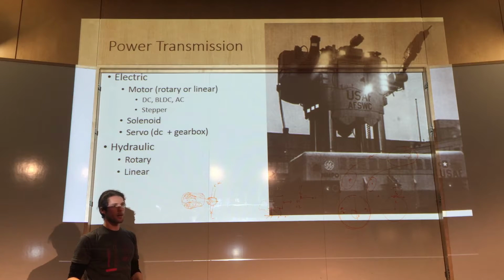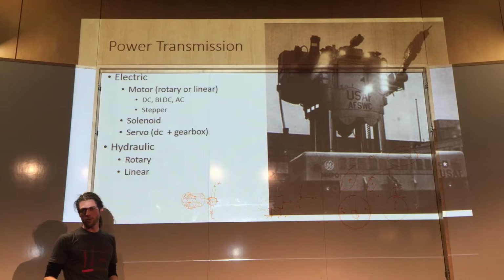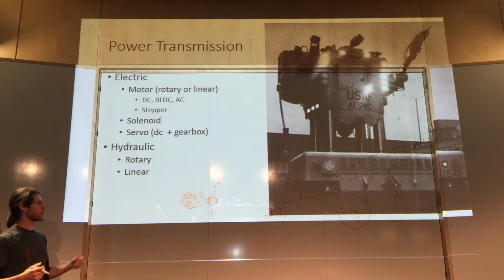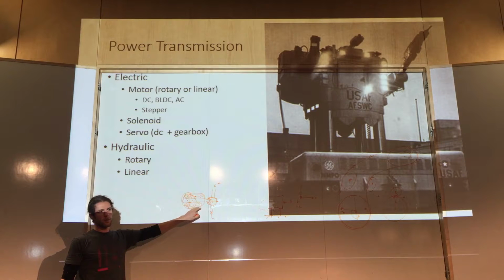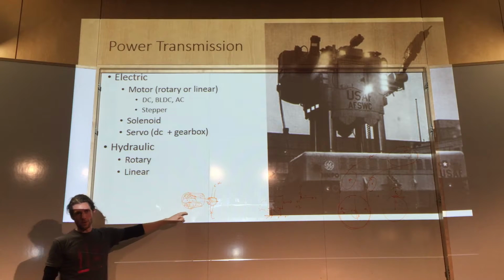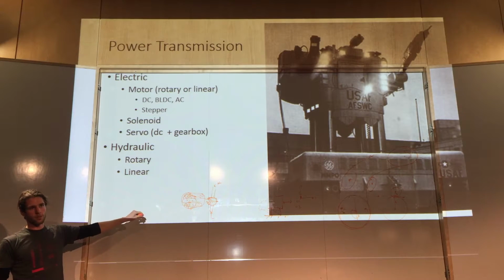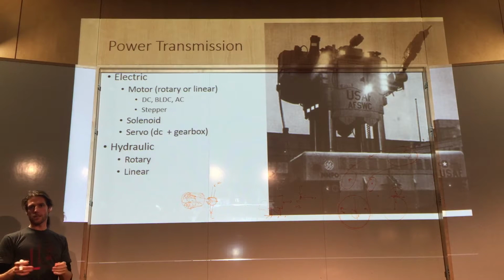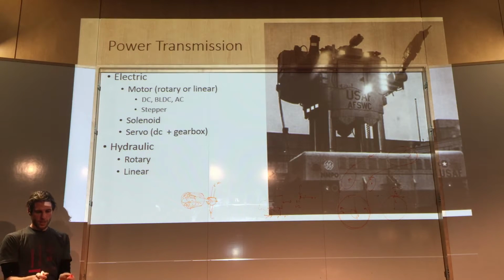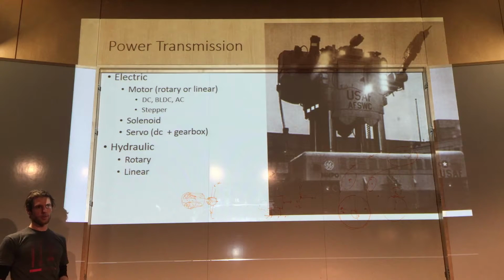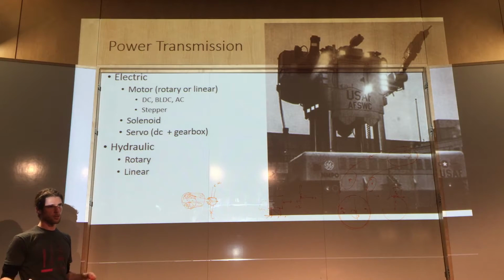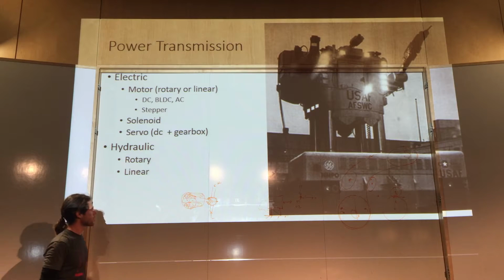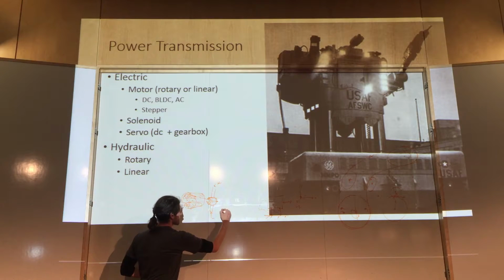And that gives high frequency noise, which ends up generating a whole bunch of noise in your system. So if you have a lot of digital electronics near your motor, you're probably going to end up getting a bunch of noise popping off from it. And right now, if any of you are building any systems with DC motors for your final projects, I highly recommend trying to get all the stuff that you're going to be using running. It doesn't have to be all finished and packaged, just put it next to each other and run it and see if you get noise, because you're probably going to have to deal with that. That's usually some sort of grounding issue or shielding issue that you can deal with. So that's a DC motor.